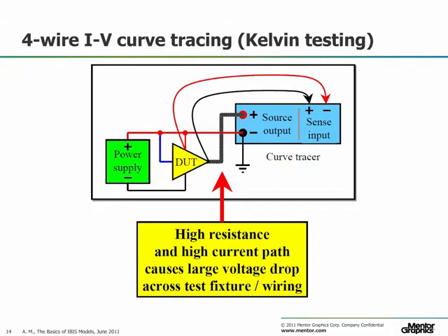If your curve tracer has a high impedance sensing input, these problems can be overcome by a 4-wire probing arrangement. The sensing input of your curve tracer would have to be connected to the points on the device under test where you are performing the IV curve measurements. If you have access to picoprobing equipment, you might want to consider removing the plastic covers from your chip and putting the picoprobe directly on the die pads of your buffer that you want to measure.